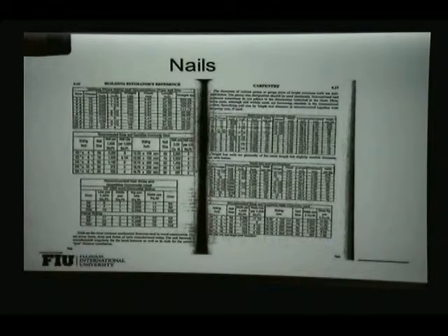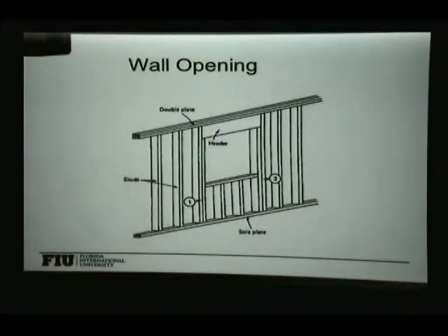Normally, if you're just getting a budgetary number or you want an idea of how much it will cost, you don't get down to that level of detail. You use a value per square foot and you move on. Otherwise, you'll spend a considerable amount of time on the estimate if you need to go down to the level of how much glue you're using and how many nails.